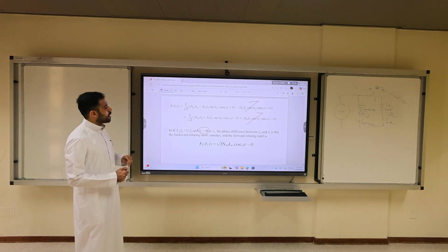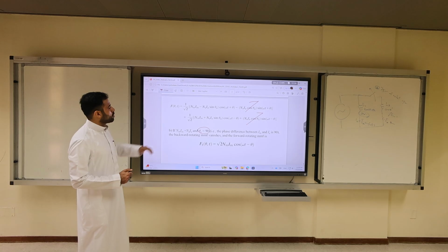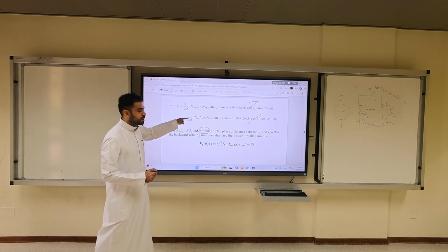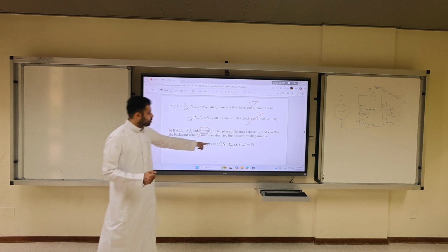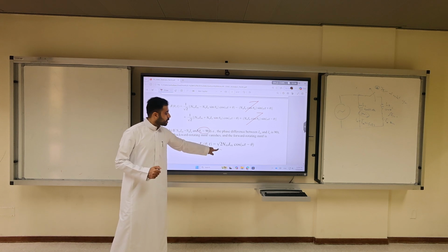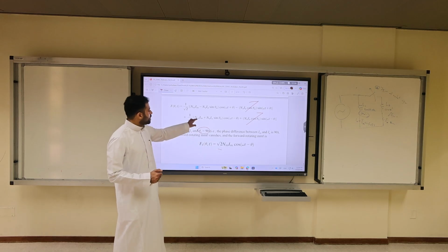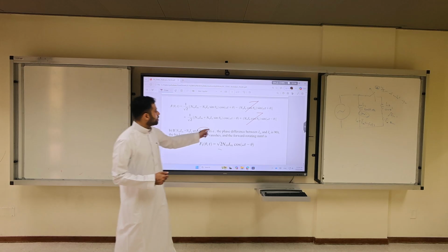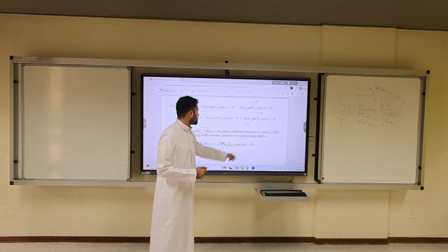And I would be left alone with these two terms. 1 over square root of 2 plus 1 over square root of 2 gives me 2 over square root of 2, which is square root of 2. Okay? Then I have N main I main cosine of omega t minus theta.